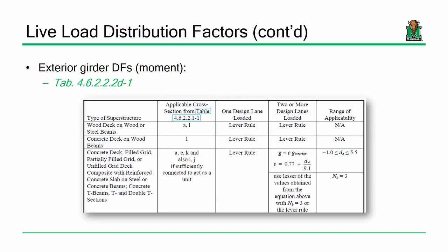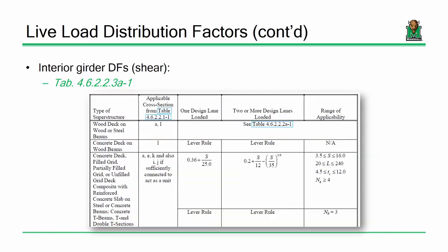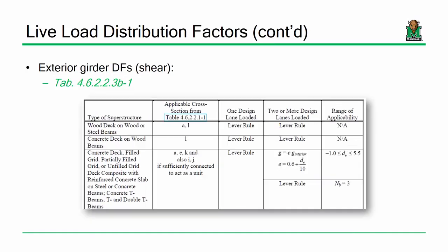So, but I'll leave it at that. All right. Interior girders. For shear, again, similar empirical expressions. Exterior girders for shear, lever rule. Now, if we've got multiple lane loading scenarios, we can also modify our interior girder factors.